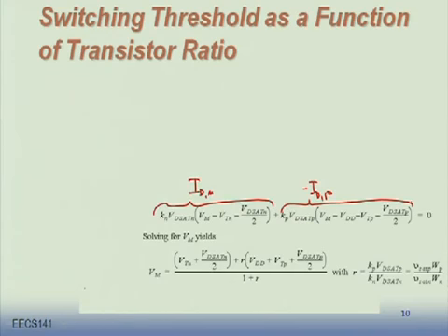Small percentage. I mean, still millions of them, but small percentage. Why? It's leakage. Because short channel length devices tend to leak. They do not like their chips to leak too much. But while the leakage was not that big of an issue, go for it. Use all minimum channel length.